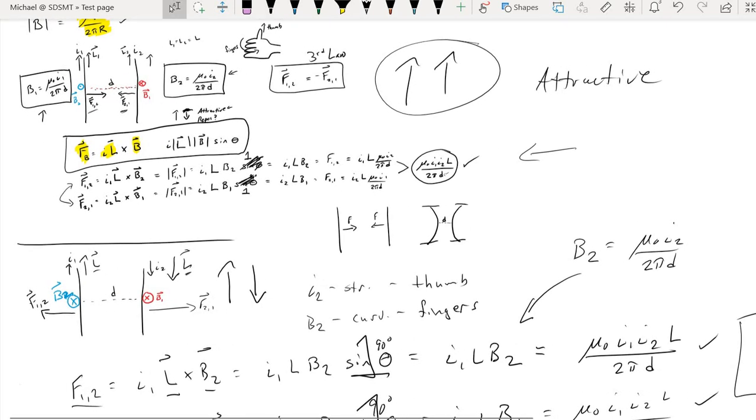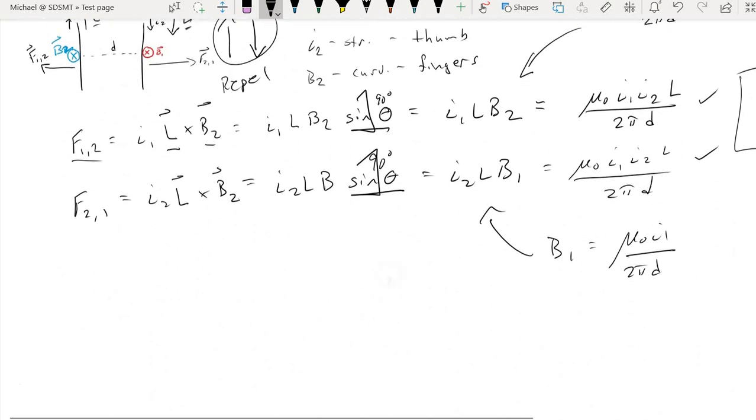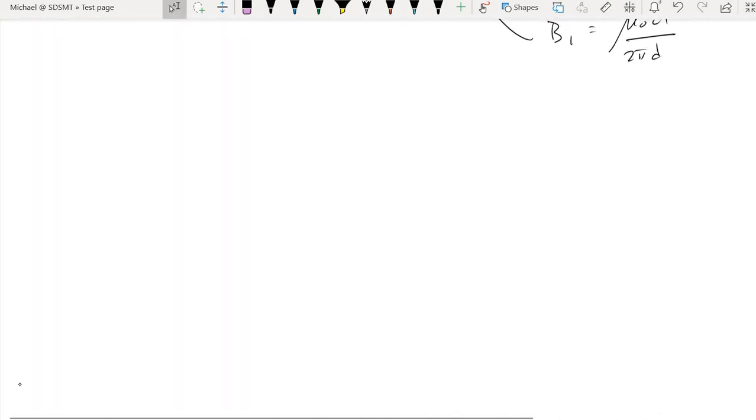In the case of the anti-parallel currents, the wires are repelling one another. Now, for the attraction case, we said that the wires started pulling towards one another, and as the wires pulled closer and closer together, the separation distance got smaller, and so the force would get larger, and we'd run the risk of possibly ripping those wires out of their connection points.